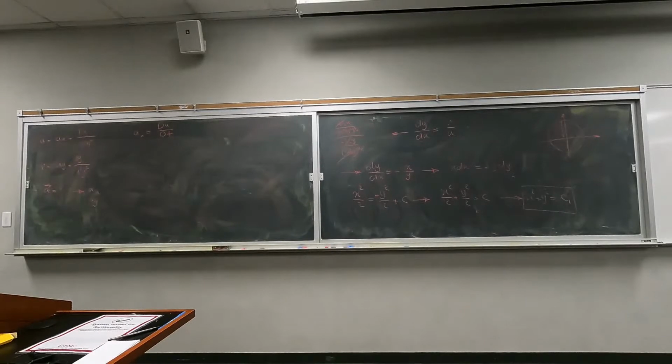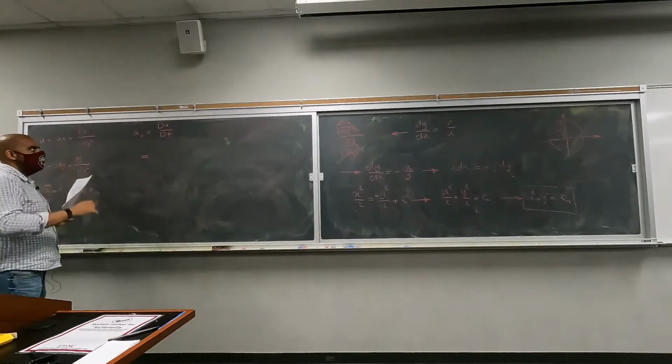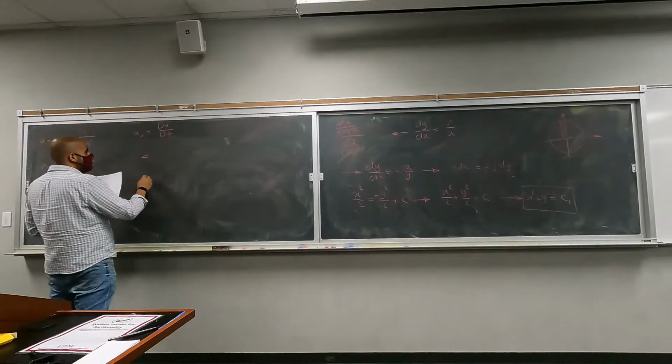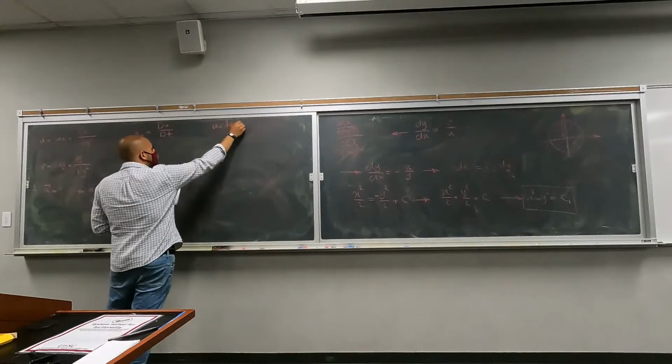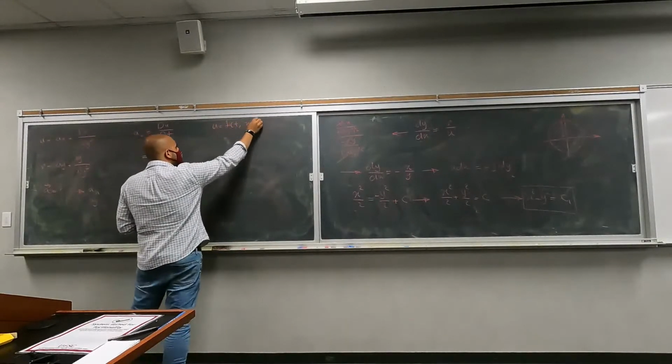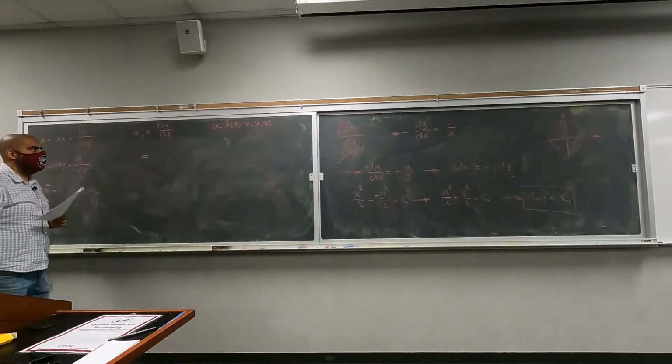Acceleration in the first direction is going to be the material derivative of the velocity in the x direction, which is Du/Dt. I'm going to write the most general form of this equation. This u can be a function of time, x, y, and z in the most general term, right?